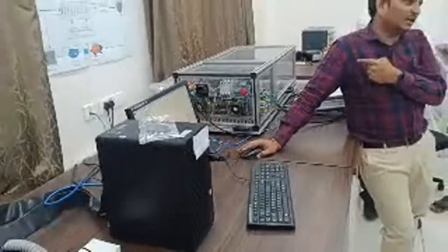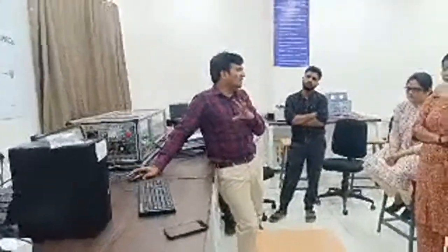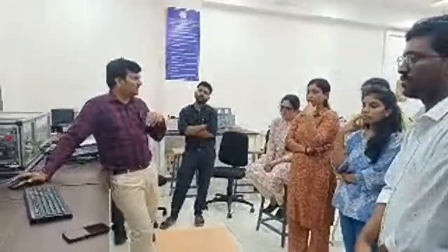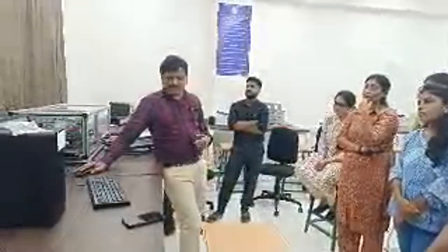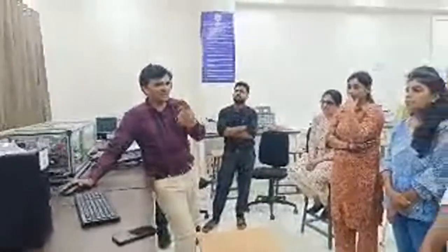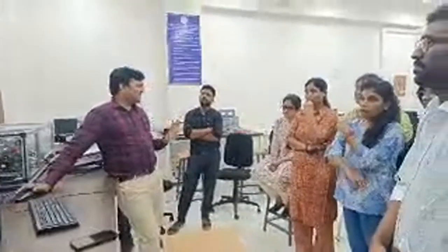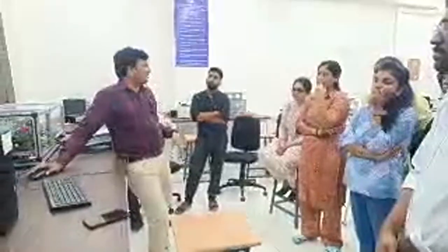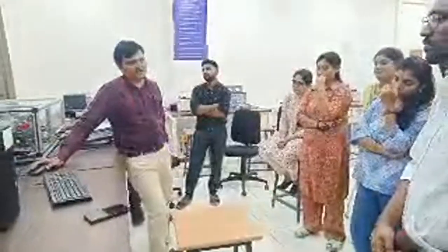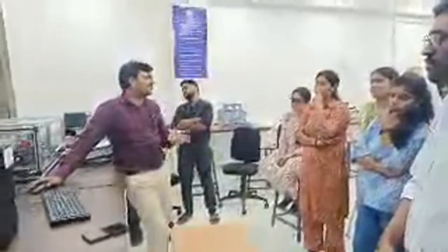Right? In real time, during the runtime, I am accessing that variable in the control desk area. That is the beauty. In other controllers, it is not possible. Once the program is done, it is over. MATLAB says you are disconnected, that's it. If you want to change it again, you have to go to MATLAB again, change it, build it, and dump it again. Those steps are not there here. You only take the control desk environment, change any variable, and run the process. That is the advantage of this controller.